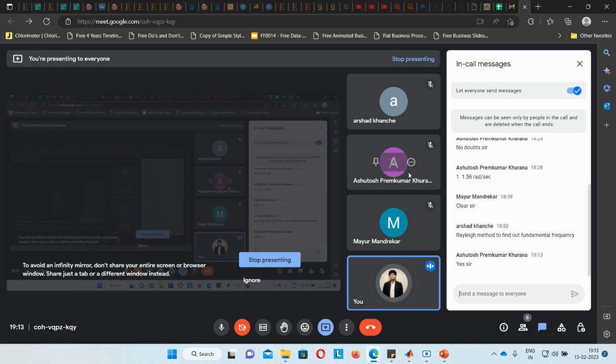Now you can also try the same thing for undercritical, critical, and overcritical damping. Just use the same question and take three damping ratios. Take them as 0.1, 1, and 2, and see what the displacement or time response is. So you will be able to visually see the effect of the type of damping on the system. Try to do these things on your own so that you understand it better. I have taught you the basics of how to write in MATLAB. Now you can go on with the advanced form of it.